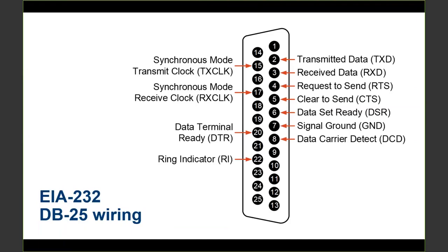So the other pins, the DTR, DCD, and the DSR, that stands for data terminal ready, data set ready, and your data carrier detect. Those are typically used for modems to help with the communications. And so we're not going to go too much into modems and these pins, because we're going to focus on the ones that are used by the SEL products, our standard SEL relay serial ports.